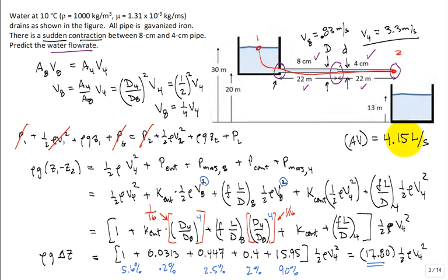Yes, sir? How do you know you need to do iterations? Well, you're stuck. How do I know what f is? I've got to get the friction factor. And the friction factor, you're thinking, okay, I know how to get it. Give me the Reynolds number, relative roughness.